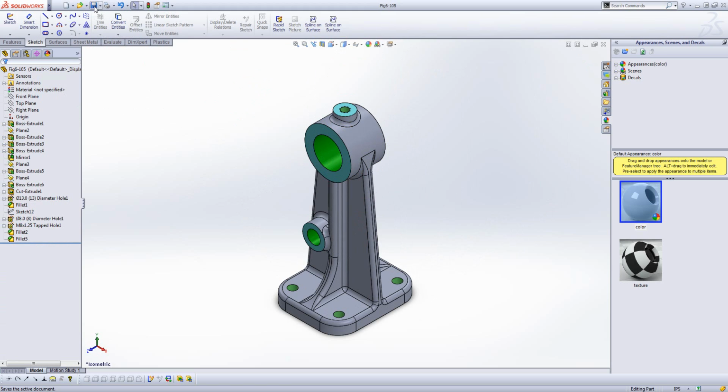Now I'm going to give this a quick save in my SolidWorks model so I have it there. You can actually create all this coloring as a configuration in SolidWorks too, so you don't have to mess up the appearance of your parts to do this. You can turn this on and off at will if you set it up right. The important part for Bunkspeed Shot is to export this as a STEP file.